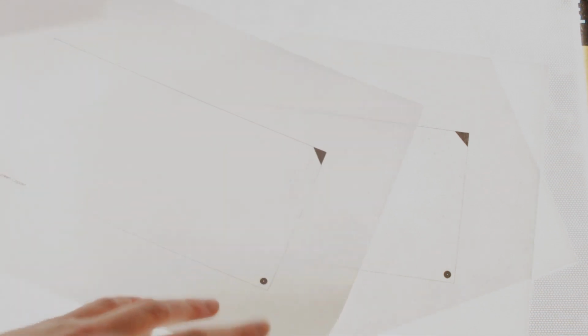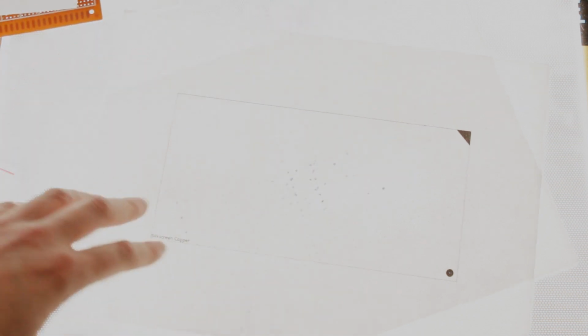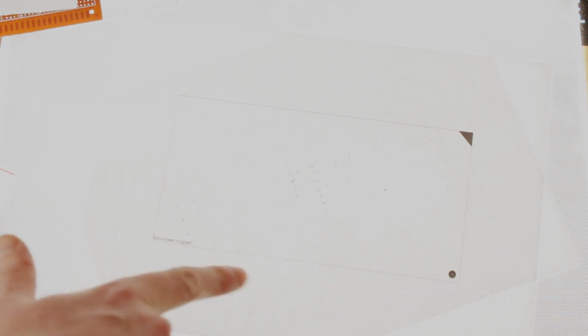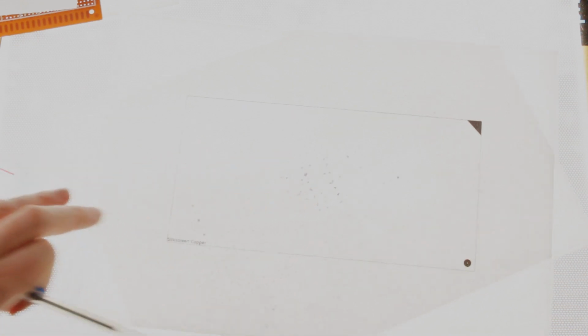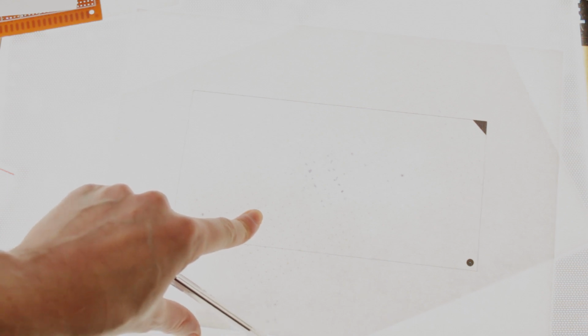I will use one of these sheets for the silkscreen. I will also use one sheet for the copper layer. I think I only need 2 sheets, so just the one silkscreen and the one copper layer, and that should be enough. So let's get started, and I will start by marking out where all these components go that have to have the right pitch.